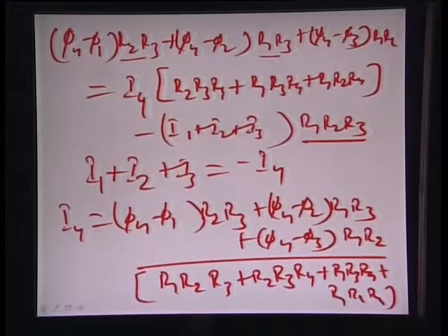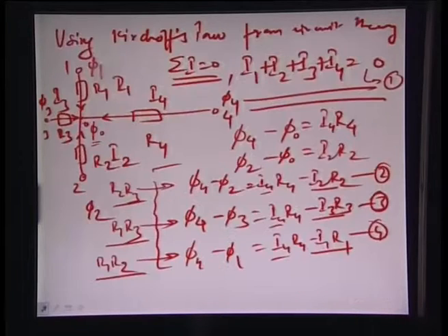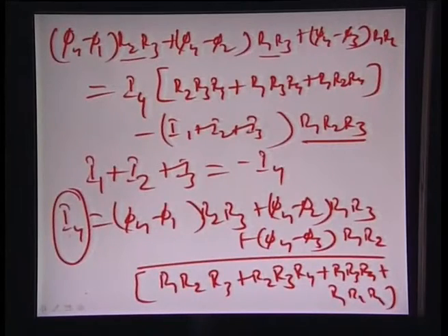Okay. So essentially we have made these equations independent of the currents, which we do not know. We do not know the I1, I2, I3 and I4 values. We have just made presumptions. However, we do know what these different potentials are. We also know what these resistances are, and the whole idea is to make this equation independent of the I's, so that we can find out from the other terms which we know already what would be the values of the different I's.